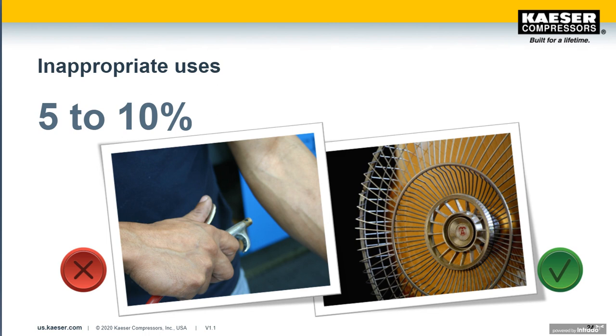For example, personal cooling has been mentioned. We have seen people that have a copper pipe underneath their desk with some holes in it. And as we all know, when you expand compressed air, it has a super nice cooling effect. However, it's very, very expensive for a cooling method. So at least nowadays, OSHA-approved blow nozzles, as we're looking at in the picture on the left, are required to prevent some of the dangers. But there still are very dangerous ways to use compressed air when horsing around, so education of your personnel is critical there.